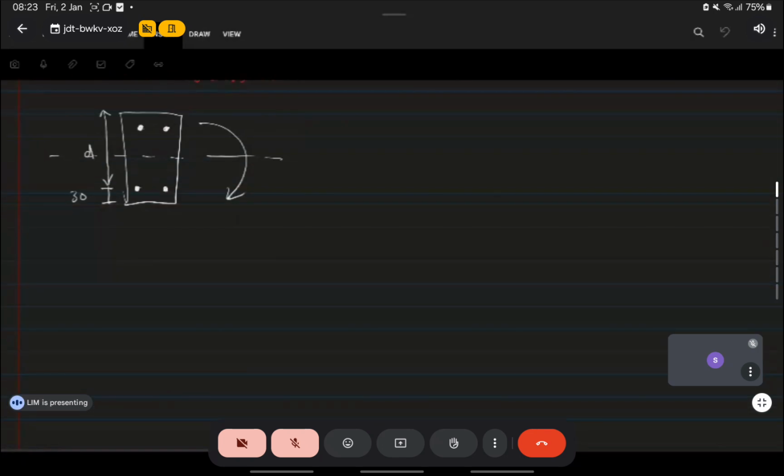So we've done beam design. For beams, we've done flexure and shear, and we've done column design. The final thing I want to cover is something related to foundation. For foundation design, I could have taught you pile cap design, but pile cap design is very similar to beam design. In fact, a pile cap is a beam. Maybe I'll just do an explanation here.